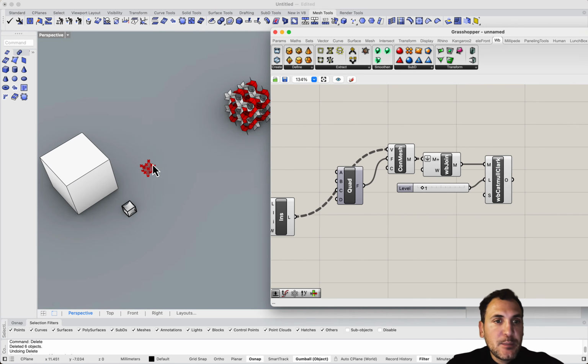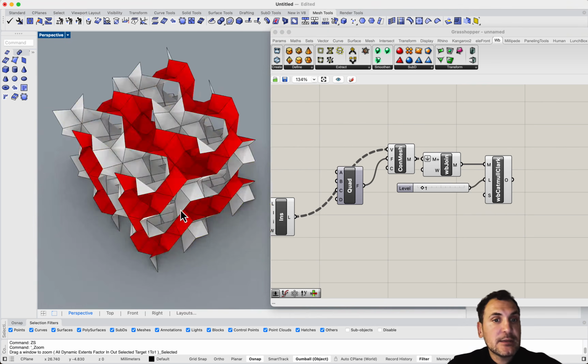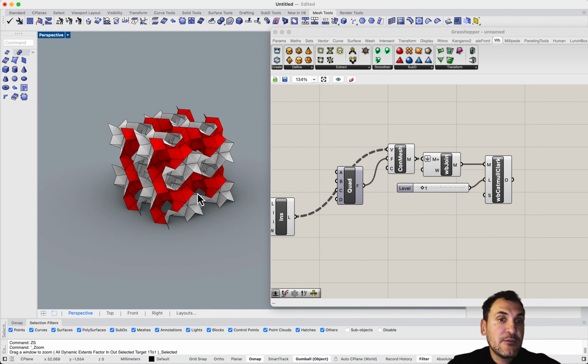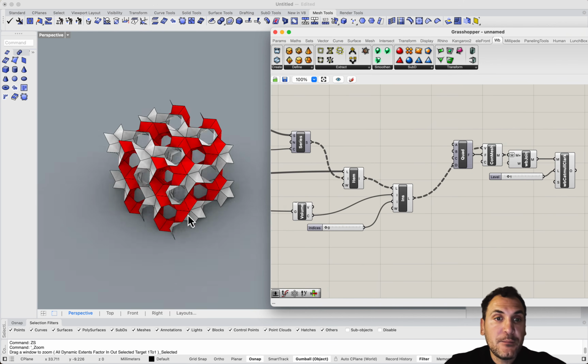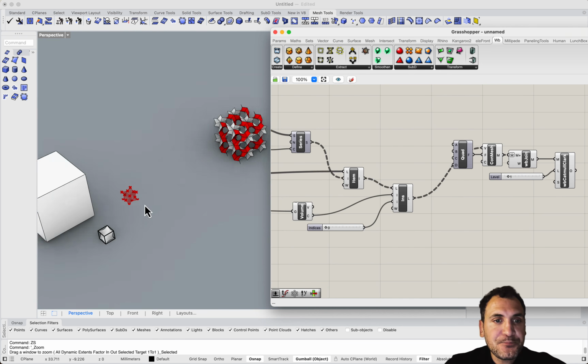Okay, next step is to actually construct something like this parametrically. And for that, we can actually use transforms. Most of the minimal surfaces that you will be looking at, same with gyroid, would have some sort of symmetry in them. There will be a module, but there will also be symmetrical components. So if you can parameterize that module, you'll be able to parameterize the symmetrical components as well. But you have to understand how to transform this geometry using symmetrical functions.